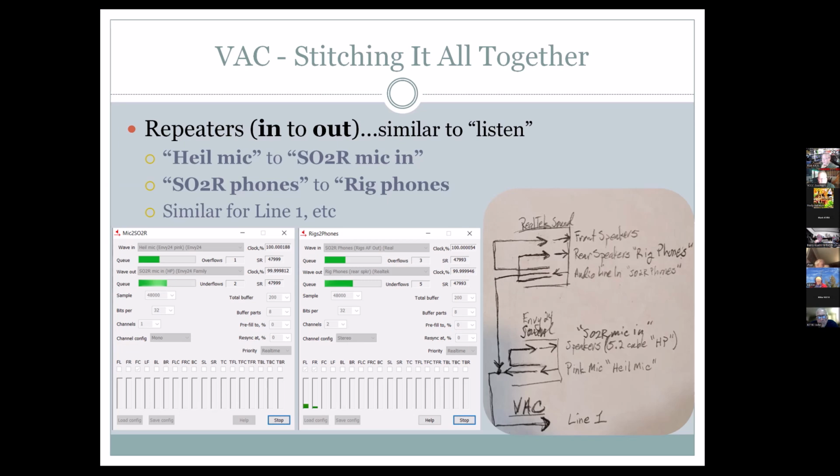Yes, it is 100% counterintuitive, and it burned me before. And that's also where, if the sample rates are divergent, if they're different, you're filling the buffer on one at one rate and on the other at another rate, and you're going to get overflows or underflows in those digital paths. So, glad you asked that question. You reminded me about that being the number one reason to pick a higher sample rate. Often 8K is available, and it's counterintuitive, but absolutely.